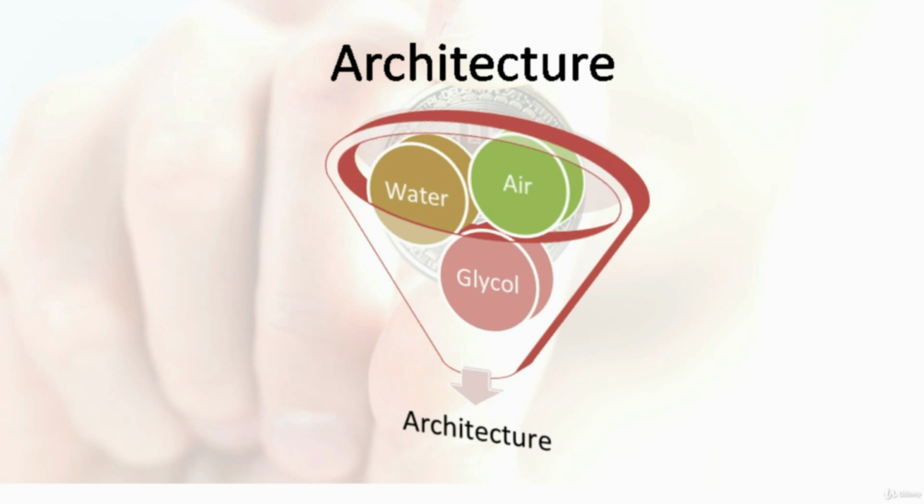The cooling architecture differences rely on differences in how heat is shared between the facility's interior and the outside environment. In the most simple configuration, we will use 2 heat exchangers, where the first one removes the heat from the air and transfers it to the refrigerant, and the second heat exchanger removes the heat from the refrigerant and transfers it to the outside air, while the cooled air is returned to the space of the mining rigs. The 3 most common architectures are the air-cooled, the water-cooled, and the glycol-cooled.